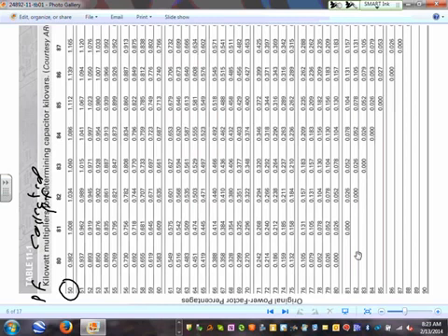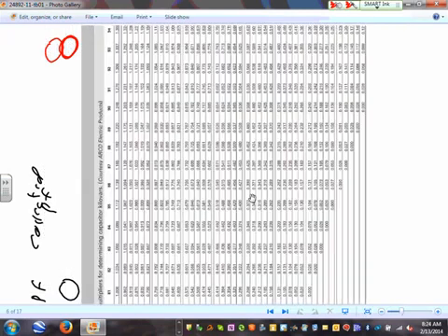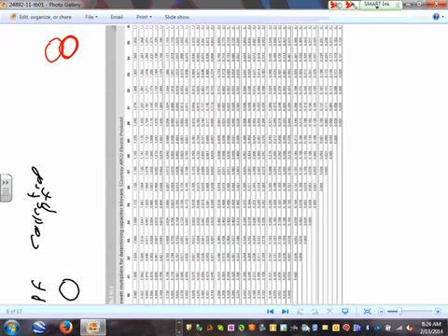Corrected power factor. So Adam, when you say go find, if your power factor is 50 and you need to correct it to 87, then the multiplier that you need to use in the table is 1.165. We're going to be using this table, guys, in a second. This table will get you the multiplier that you need to correct for the power factor. Everybody got that? This is a great table to use to get the multiplier that you need.